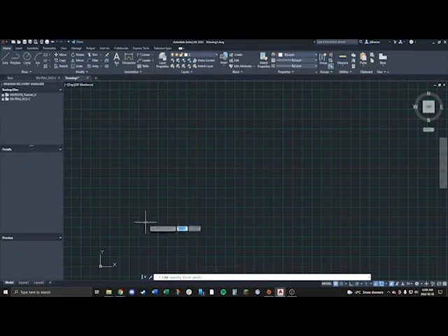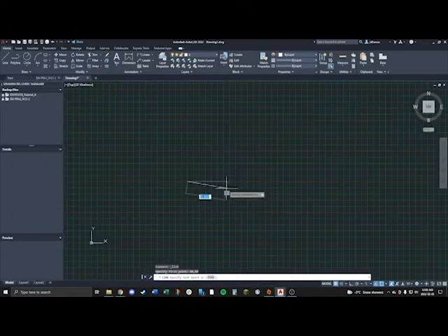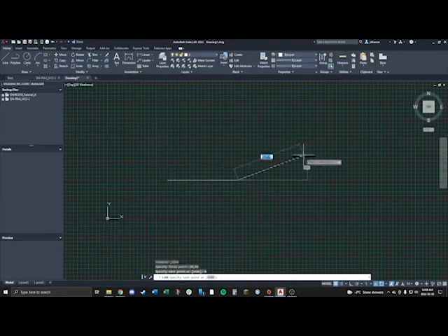So last assignment, we were given specific instructions to start at 80, 50. So I'm just going to type that in now, 80 tab 50. It's going to snap me over to here, and it shows me that the first line is 94 at an angle of 0. So I'm just going to type that in, 94, tab 0, enter.